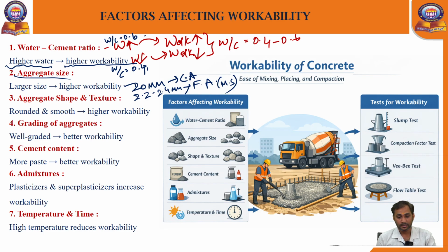Okay, done. So how are you taking? Let us take 60% of 40 mm size aggregates and 40% of 20 mm size aggregates.